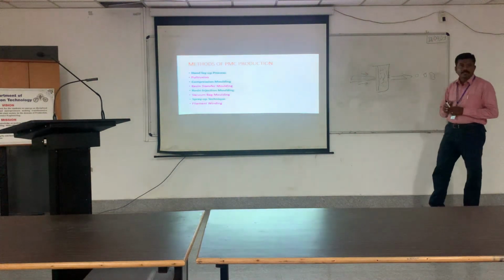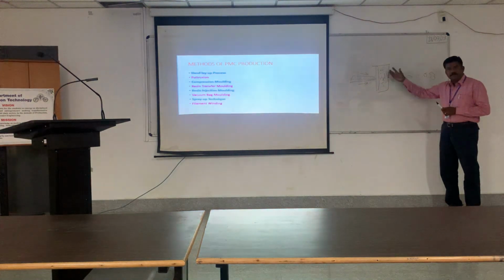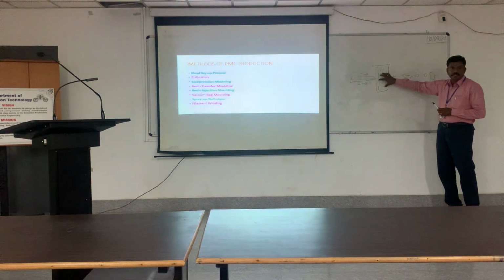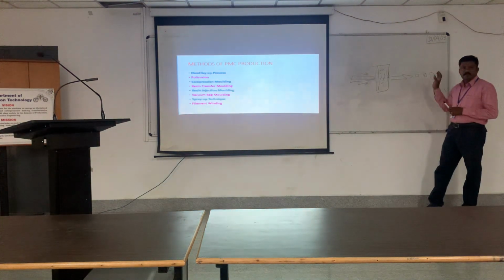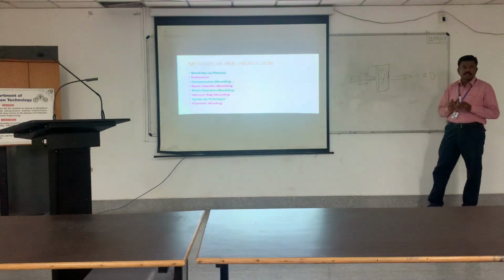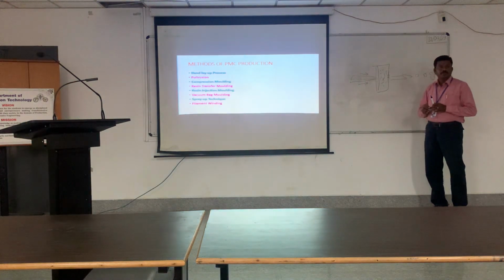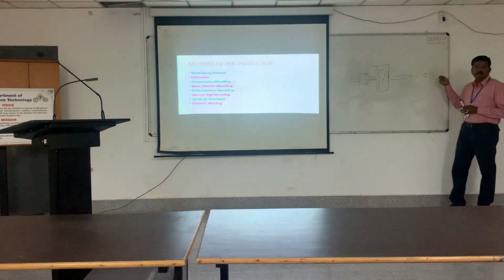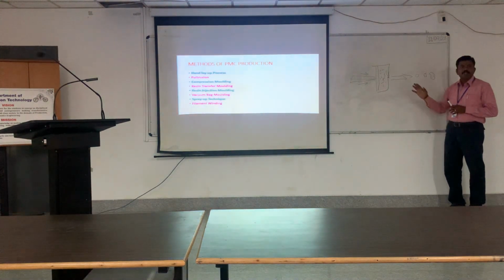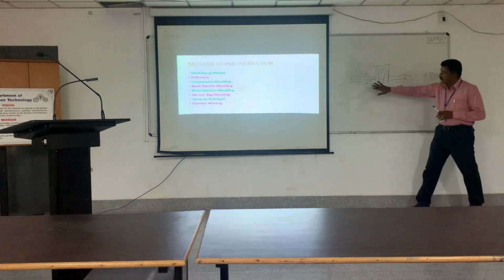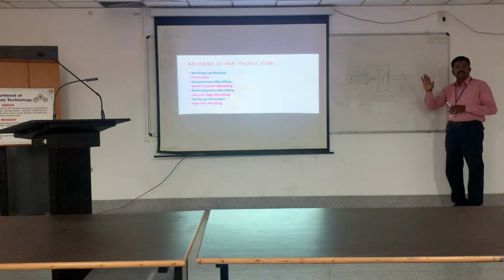In the case of composites, the same thing: the composite mixture, matrix and reinforcement are mixed together and placed here, and if you push it, the job will come out. That is called a simple extrusion process. Instead of giving a pushing force, you can pull the component out. Here, when you give the push force and the job comes out, that is called pushing extrusion.